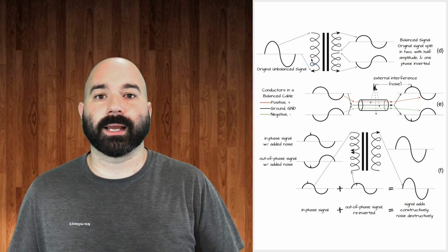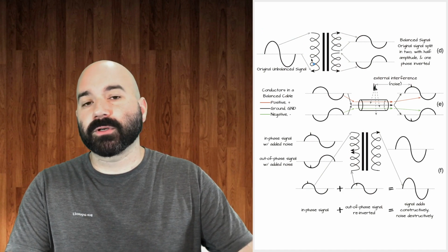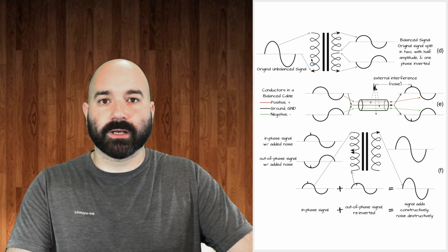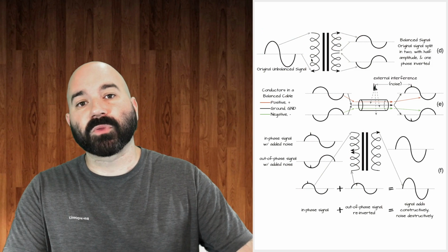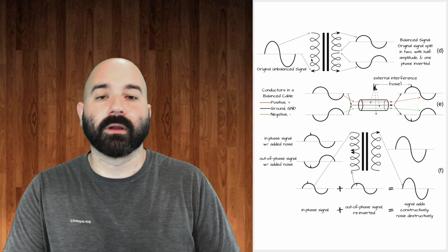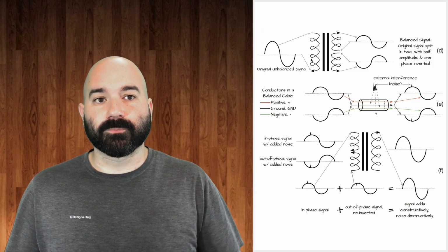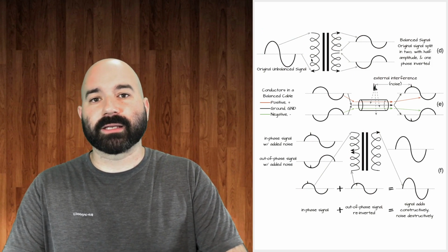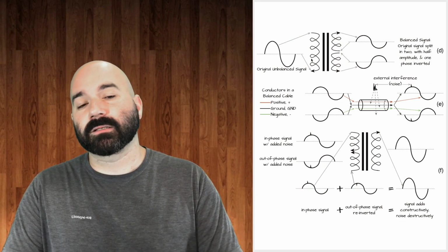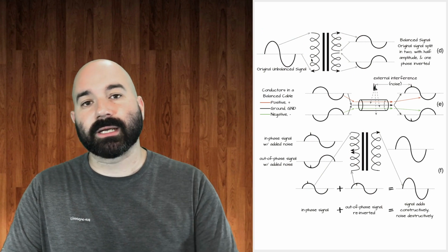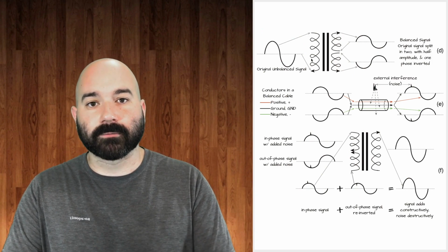Now you're probably wondering, how do you do this? What does this? And the first one is the DI box. We've already talked about a DI box, the direct box. Not only does it match impedance, but it will also turn it to a balanced signal. Not all DI boxes will, but for the most part, they will. And how do you tell whether or not a device or instrument outputs a balanced or unbalanced signal? Simply, it'll say on it. It'll say balanced or unbalanced, or for short, just BAL or unbal.